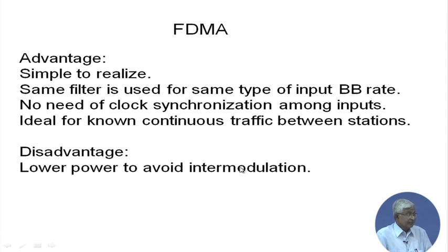We will discuss that in much more detail later, but to avoid those spurious, you have to go back to the linear region, which is called back off, and back off means you will be transmitting less power. So therefore your EIRP will actually be lower than the capacity. That is to avoid those spurious. So it will be lower EIRP operation.